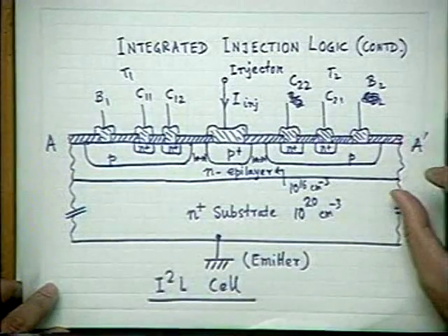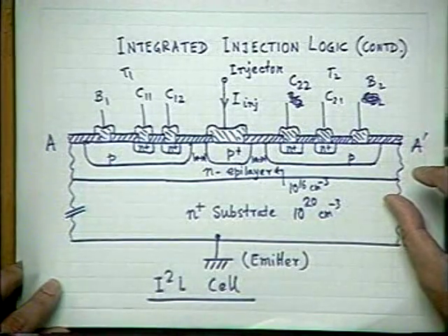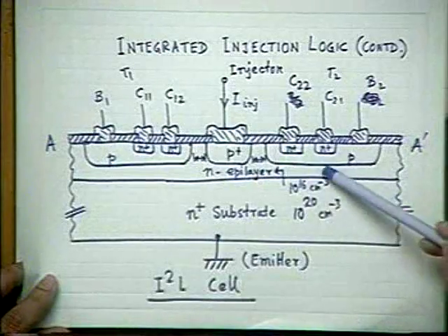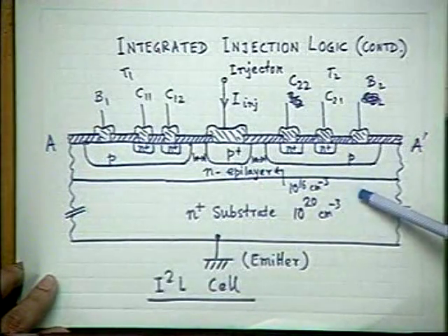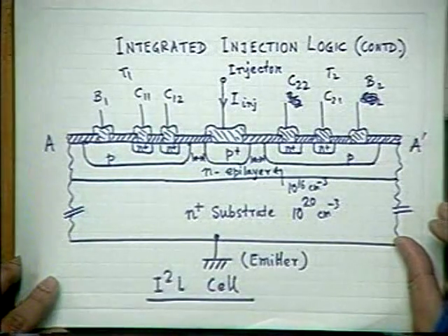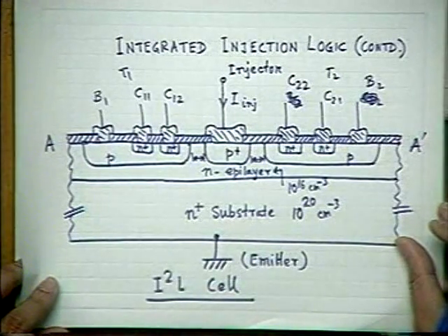So this is a problem, because you want to achieve a very high gain, which is very important for getting high speed, a high gain bandwidth product, as well as a very good shape factor and a very good noise margin. In that case, this low current gain will matter. That is one of the drawbacks of I2L, that it may not offer you a very good noise margin unless you are very careful, and the speed is intrinsically less.